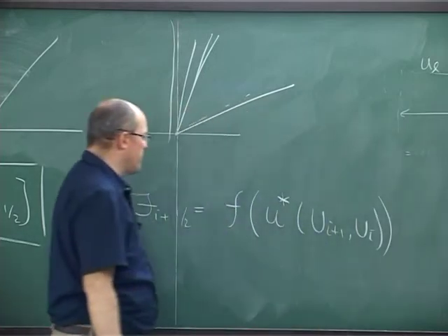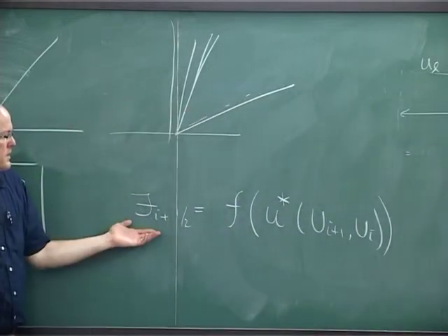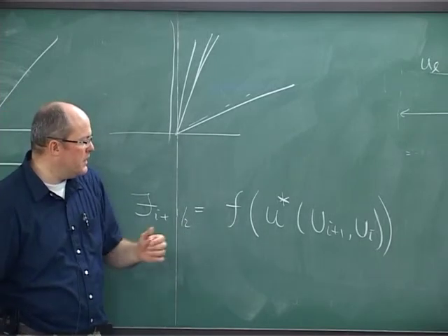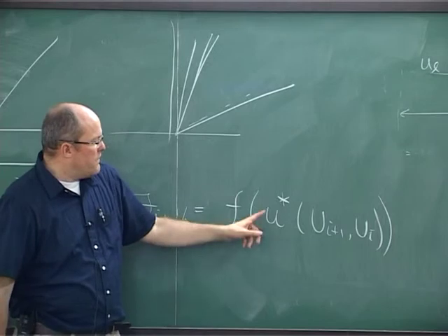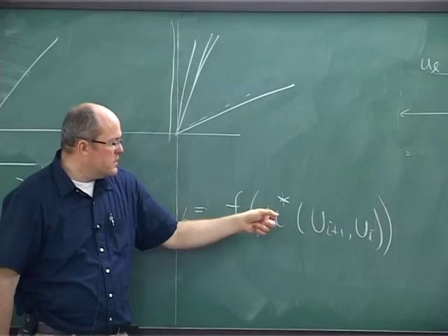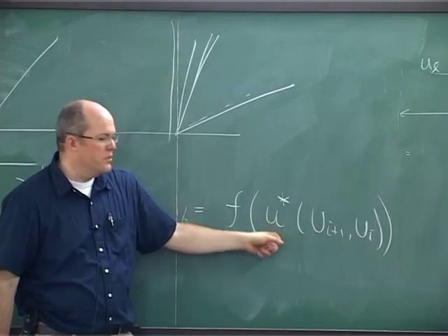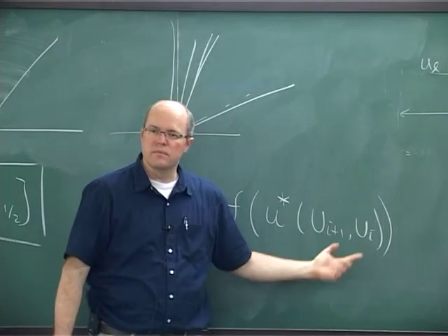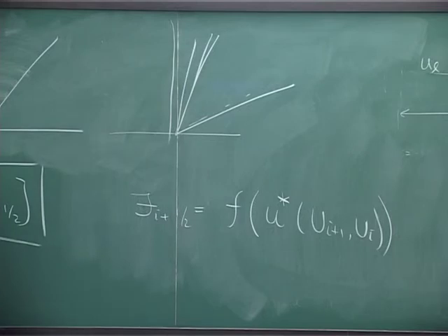So sometimes people will write it that way, that the numerical flux is simply the flux function in the PDE evaluated at the solution of a Riemann problem whose right and left states are those two. So this complicated integral in the numerical flux, I actually don't have to do. And so that's what makes this method work out.